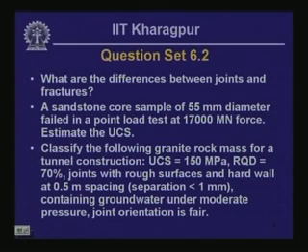These things remain in the rock mass, and these features we are going to call by the keyword joint, whereas fractures develop later on during the lifetime of the rock mass because of relative movement between different portions within the rock mass. So that is the essential difference between joints and fractures.